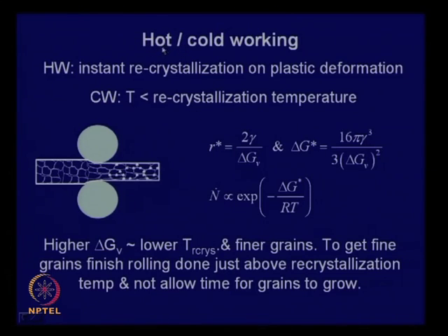If you recollect your last lecture, we talked about thermomechanical processing. If the working is done above the recrystallization temperature, we said it is hot working, and the bulk of the deformation from the continuously cast billet is done through hot working. Cold working is often done in the finishing stage, and often after cold working the steel may have to be given some amount of annealing to relieve the stresses or to get a recrystallized structure, for better ductility or the best combination of strength and toughness.